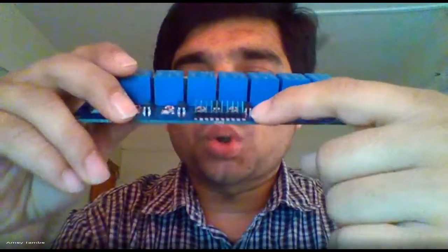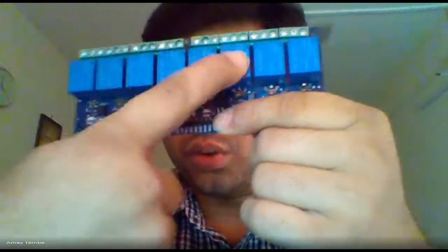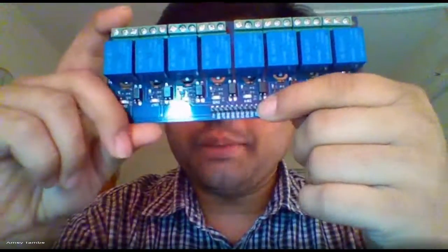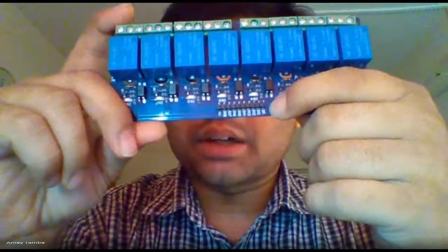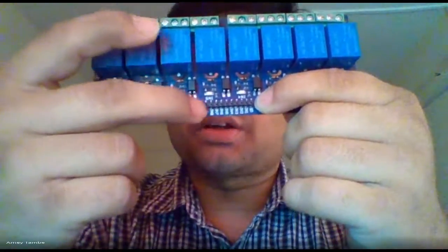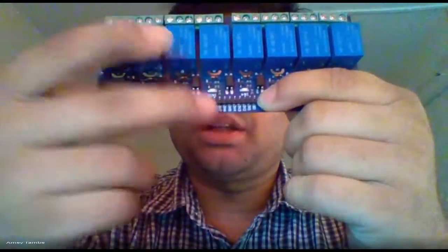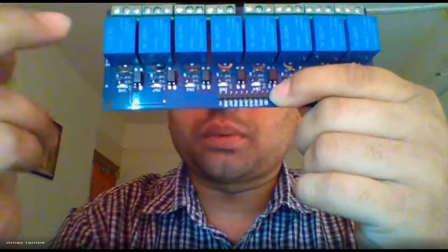Now on the relay you can have some pinouts. This is the 8-port relay, so 8 relays you can see. On the 8-port relay, you have one pin as ground and one as VIN or VCC. VIN or VCC will require 5 volt in, and the other pins are the relay pins. Each pin denotes one relay. So you can define pinMode relay 1, pinMode relay 2. It means that in your program you are defining which work each relay is supposed to do.